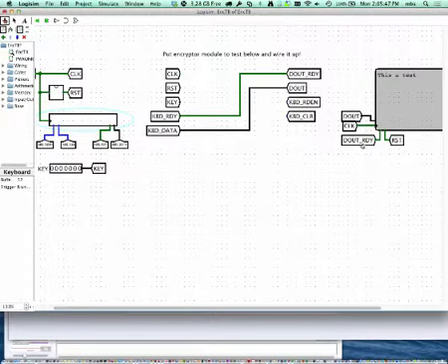There is D out and D out ready. And again, the idea is that whenever D out ready is high and a clock edge comes, then D out is read in and displayed out here. So whenever you want to write a character, you put the character on D out and make D out ready high for one clock cycle. If you make it high for more than one clock edge, then multiple copies of that character will appear.